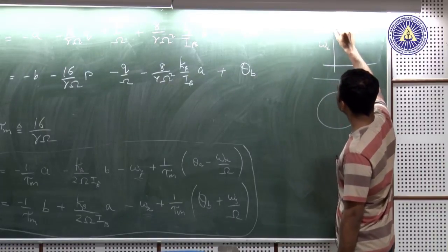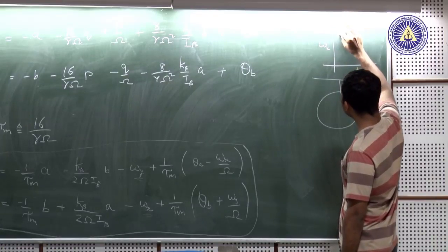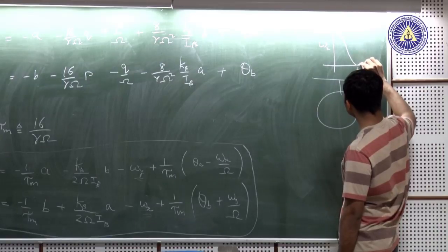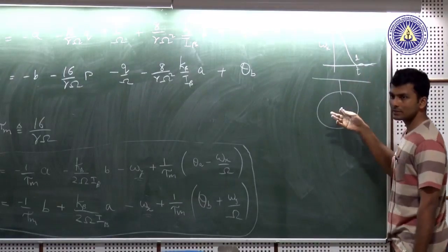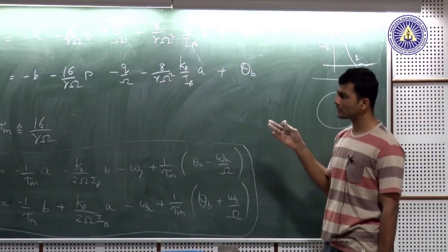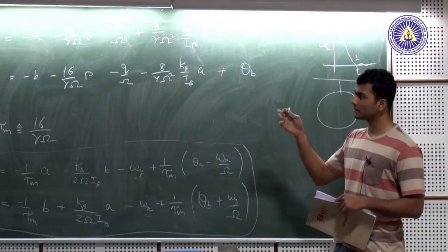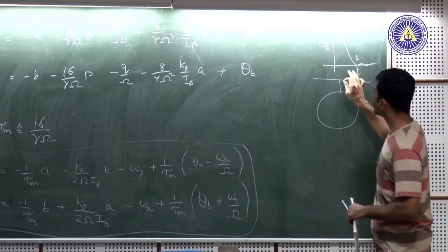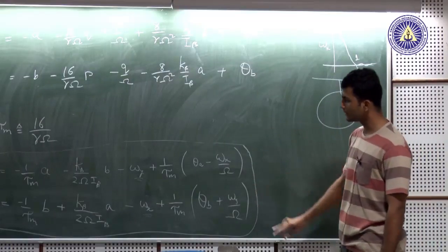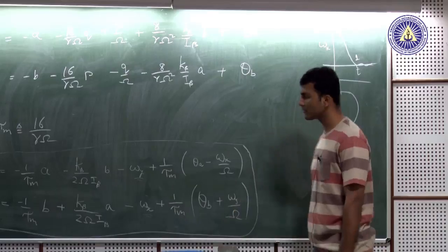If I initialize my omega x as this, it would damp down to 0 in almost 1 second for the small scale helicopter that we have seen previously in the video. So that is the kind of damping there is in this system, with the kind of numbers associated with these parameters.